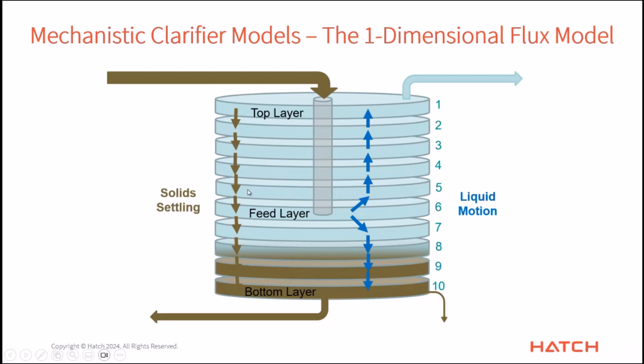And so as you'll see in the settling curve, we need a minimum amount of concentration for flocs to form. And then there's kind of a peak sweet spot where they settle quite quickly as they're flocking together and falling down. In the high concentrations down here, they don't settle as quickly anymore, as it's now kind of into that layer of sludge and compression settling and compaction down there. Right. Okay.